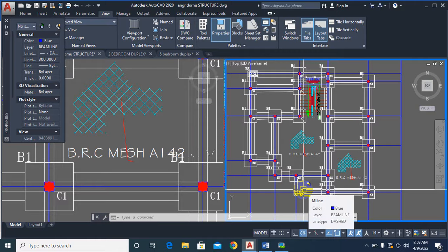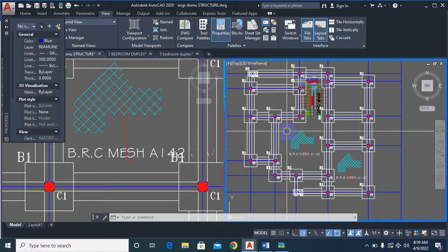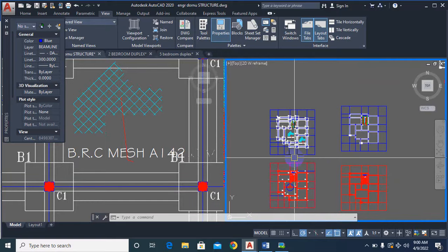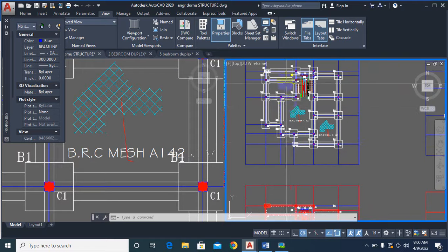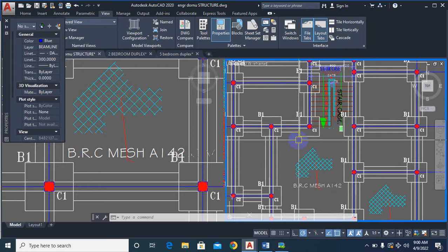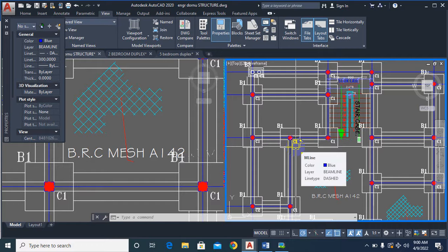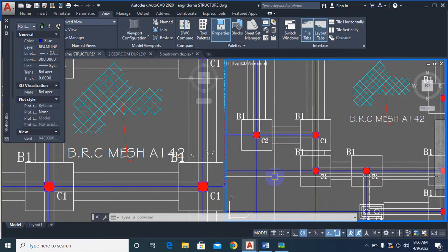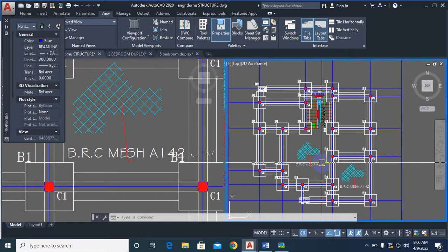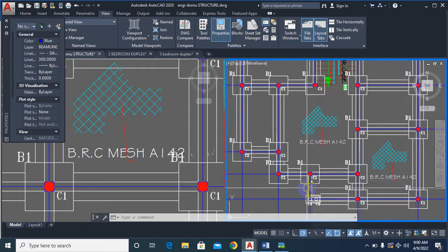This general arrangement that I have done will determine the cost of this building as far as the structural members are concerned. It will determine the number of reinforcement, how many columns, the number of beams, the sizes of beams, because right now I'm assuming all of those sizes. By the time I run my design, if any of these structural members fails, I'll have to provide another section for that particular structural member.